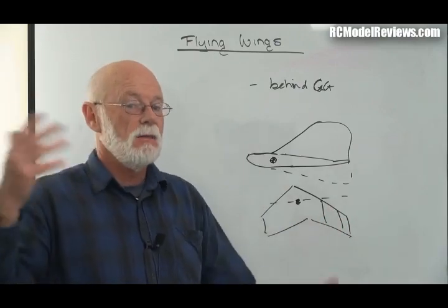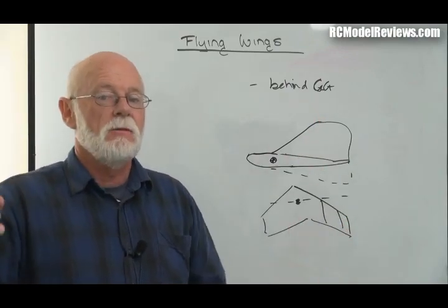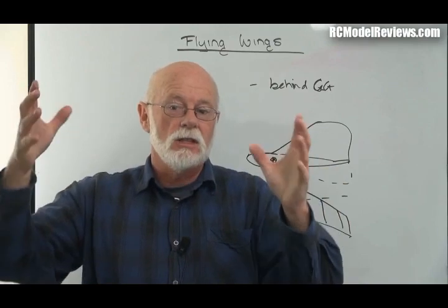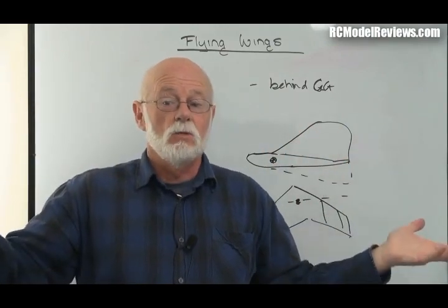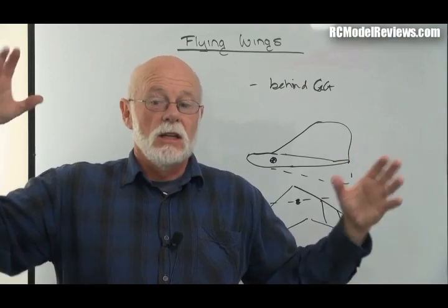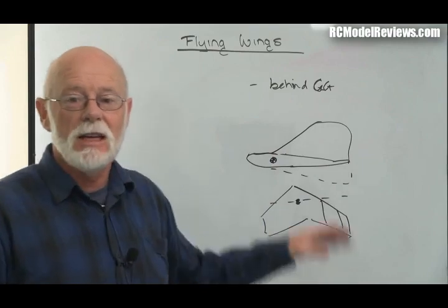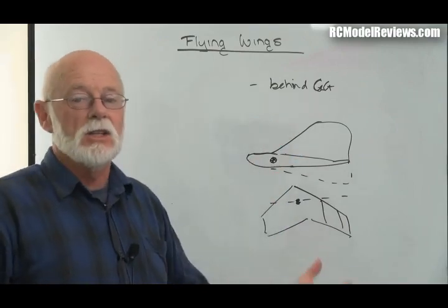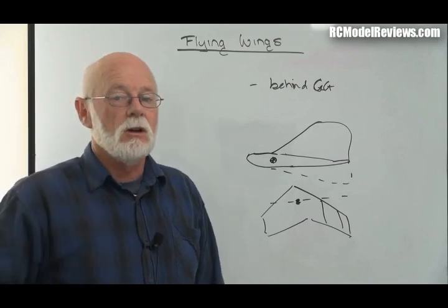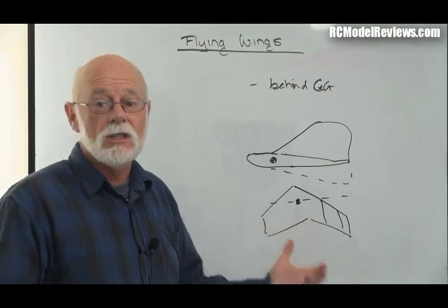How high are the fences? Whatever. You have to practice. But, you know, just try stuff out. See what works. You can get some foam board, cut it to shape, a couple of dabs of hot glue, just enough to hold it, fly it, see if it improves it, increase the area, see if it gets worse or better. And then you can trim it down to get the minimum size you need to make it work. That's the fun of this stuff. You can experiment. You're not like McDonnell Douglas Skunk Works where every change costs millions. All it costs you is a little bit of hot glue and foam board. It's worth playing around with. And it's fun. It's something exciting. You learn something as you do it.